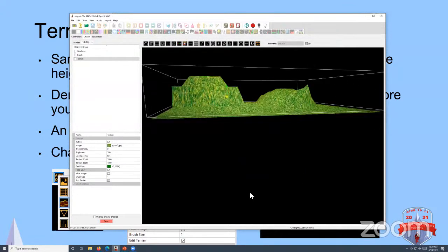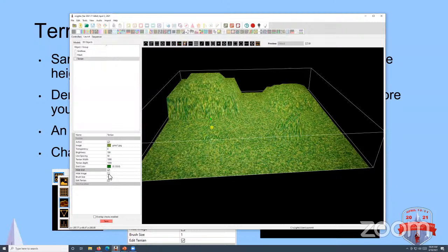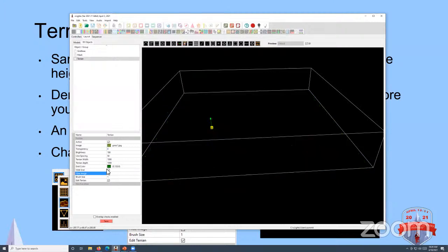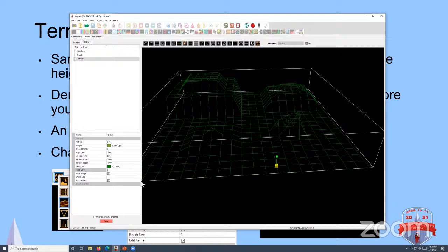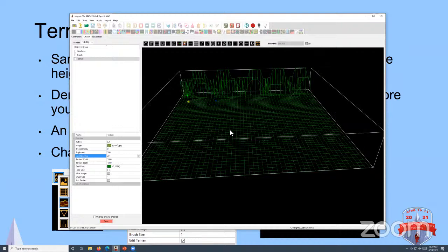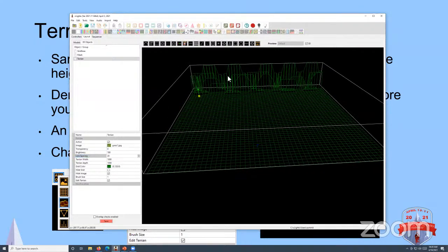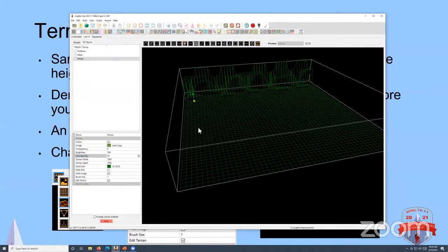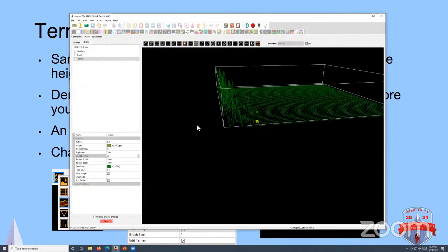One thing I will recommend, I'll show you why right here: if I come in and tell it that my line spacing is denser, say now it's 20 pixels, it's going to do that and make it denser, but it took all my existing points and left them in the array the way they were, so now everything's scrunched.